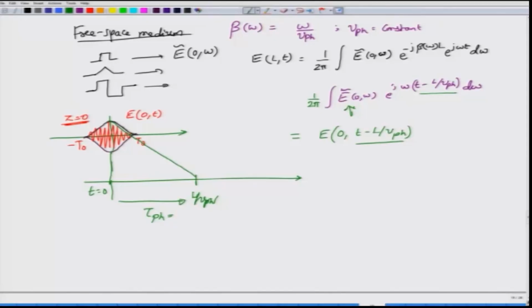All frequency components arrive at the same time, and when you put the frequency components together and form the inverse Fourier transform, you would see that the output would remain the same as it was at the input. No distortion, although I might not show it correctly, there is absolutely no distortion, and the pulse would remain without any change in the pulse spectrum. So, no change is an important condition. Okay.